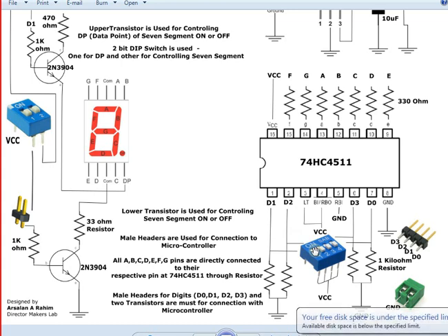But when you are going to make the PCB, this is very important, you are actually going to connect a male header. What is a male header? A 4-pin male header with a spacing of 2.54 mm, that is standard. So you are going to have this connected on D0, D1, D2 and D3, certainly in order: D0, D1, D2, D3.